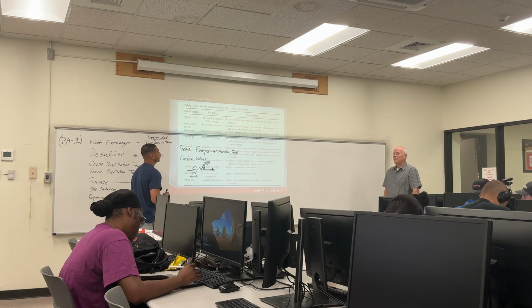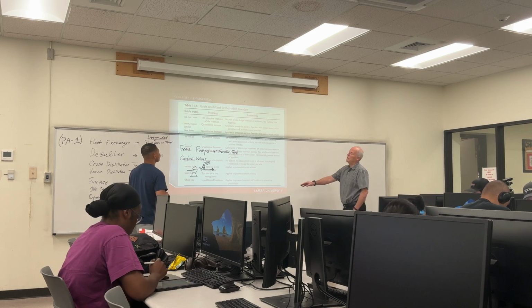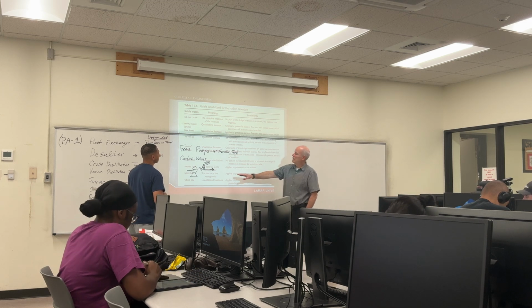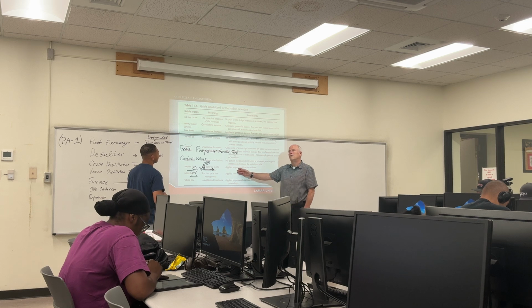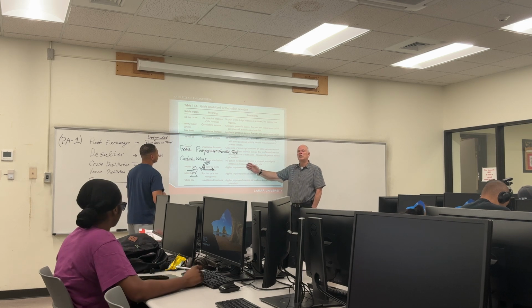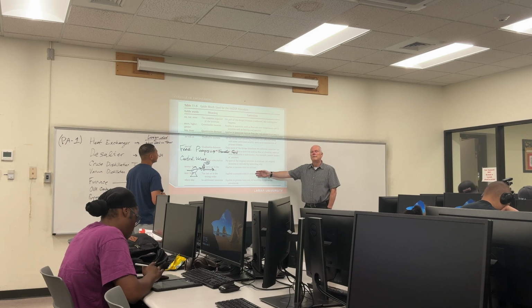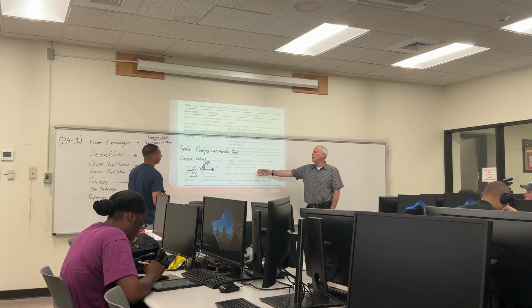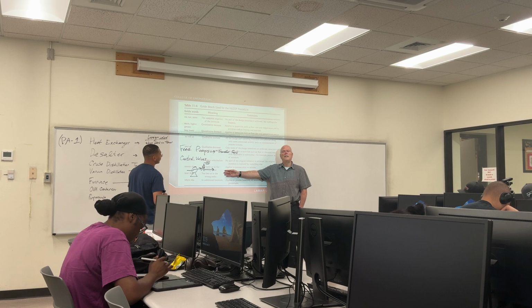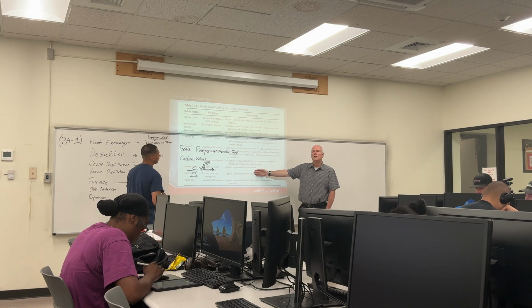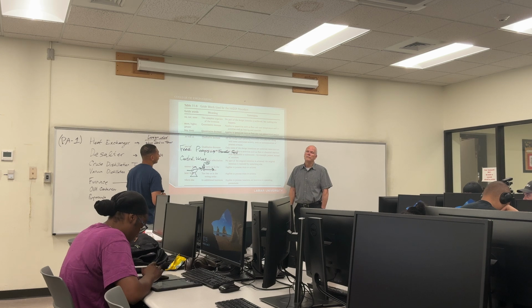Yeah, there's a lot of stuff in between, but when it goes to the desalter, then it goes over to what did it go next? Goes to a whole bunch of exchangers and then it goes to a furnace, right? So what happens if this pump shuts off feed and then you have no flow through the furnace? Furnace just gonna heat itself up. Fail. Boom.